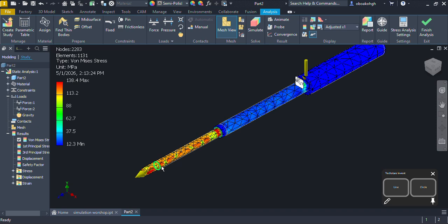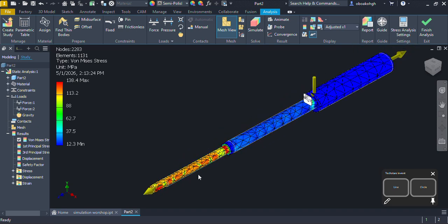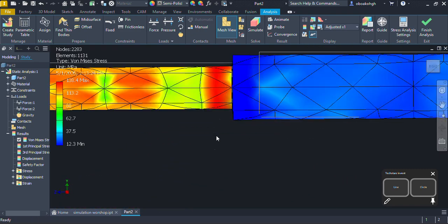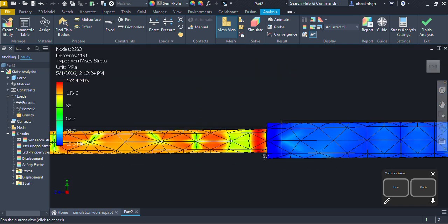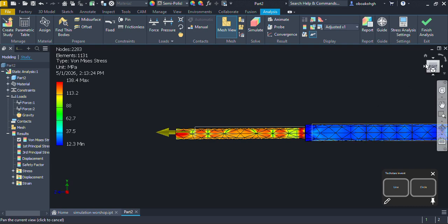Because the diameter here is the smallest as compared to the second section and then the third section. The pull is on both sides, 35,000 Newton on both sides. But here is more red because the diameter is very small. So if there is any fracture to happen, it has to happen here. That is why you can see at this particular step that this is where the reddish zone is more. So this is what is actually going to happen over there.